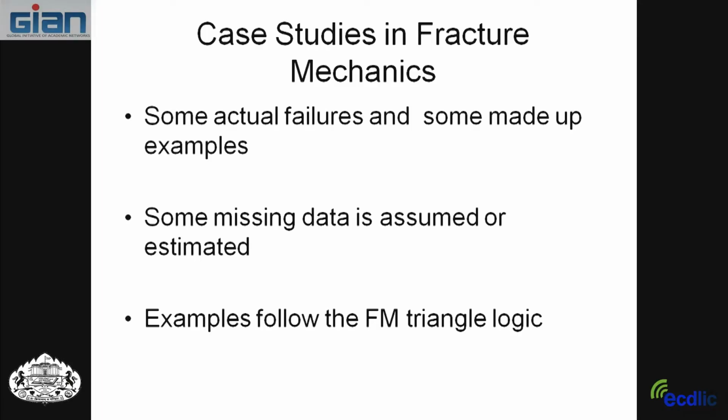Some of them I didn't have the data for, so I estimated it. But all these examples follow the fracture mechanics triangle logic. Remember the fracture mechanics triangle: stress on one corner, defect size on another corner, and material properties on the third corner. And usually you have to know 2 things and try to find a third.